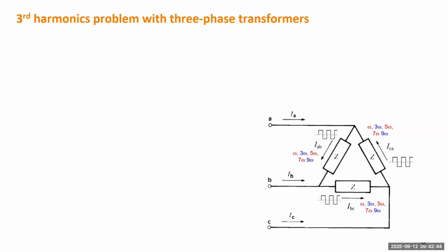The next one will be the 15th, but this is too high, so usually we can ignore it. You don't have to consider very high order harmonics, because the higher the order, the smaller the magnitude. So you can stop somewhere. Usually 5th or 7th should be enough. Third order harmonic is still significant.